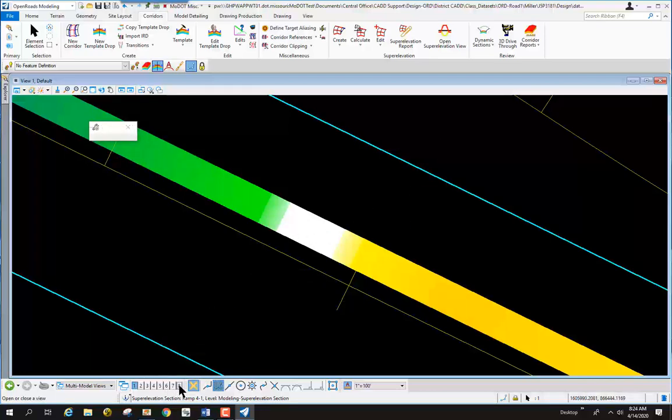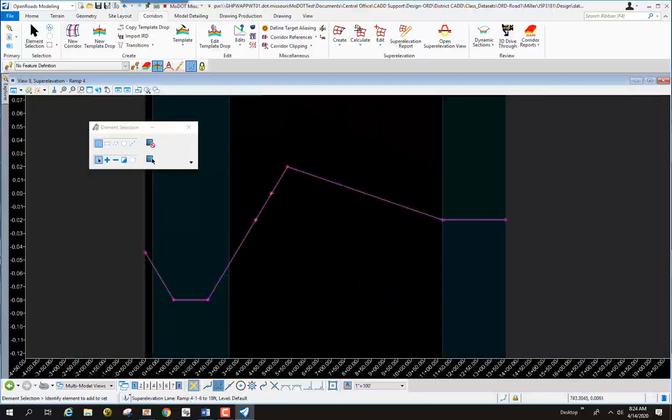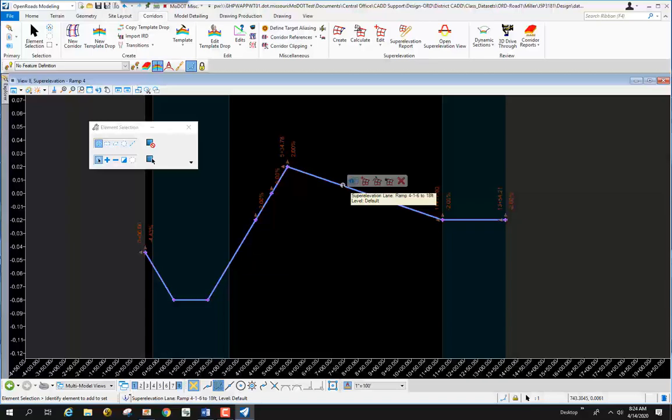I'm going to go back down to view number 8. I'm going to click in there again and place it. So we're going to go ahead and click on the profile control line, and I'm going to go to the heads up tools properties, and in step number 14 we're going to change the inside edge offset of the remaining shape that's out there. We're going to change it from 6 to 0, and then we're going to change the width to 18 to match our template.